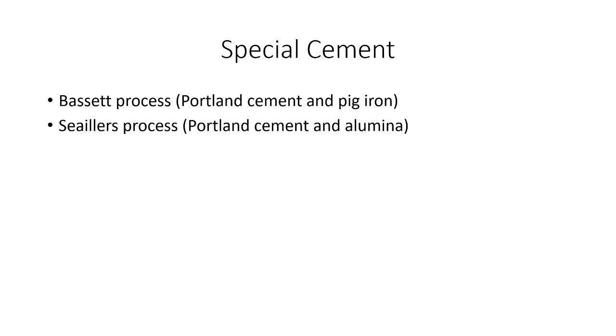And the product is treated with sodium carbonate solution to dissolve alumina. Okay. And the solid residue is then mixed with additional limestone and reburnt to give cement clinker. Alumina is recovered from the extract solution as the byproduct. So this is, you can say, another byproduct of the cement.